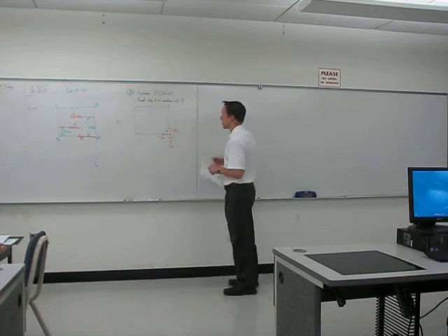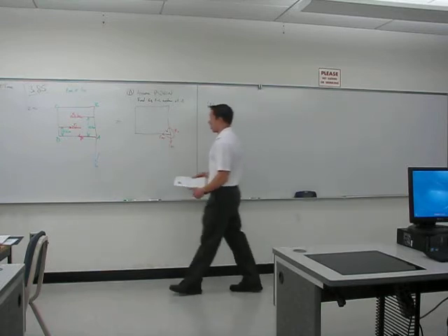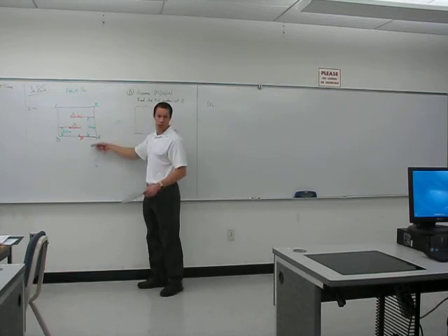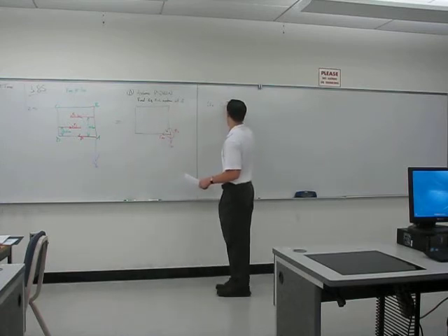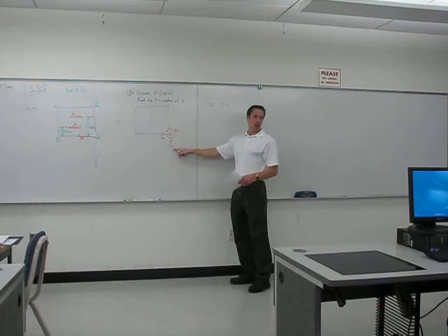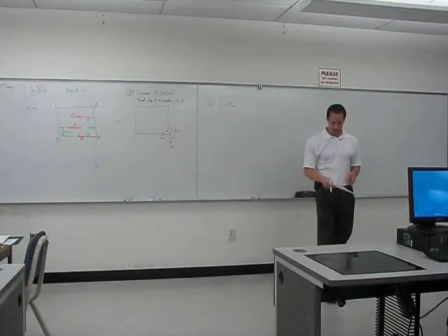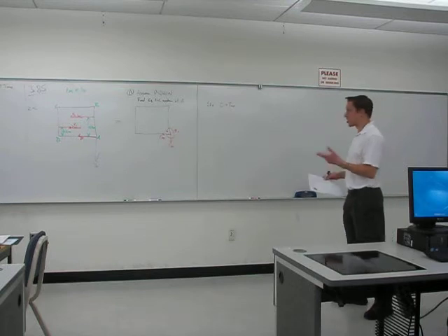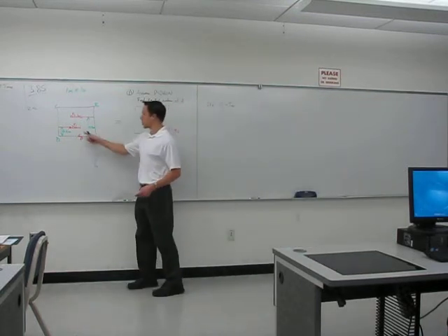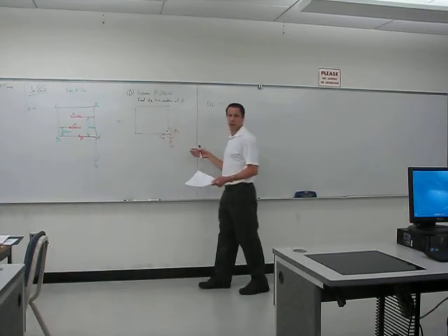So we might say the sum of the forces in the x direction. Okay, so the x direction, positive x is going down. Nothing is going in the x direction in this picture. All the forces are horizontal, so they're all in the z direction. So I'm going to have 0 on the left-hand side equal to, in the x direction, FAX on the right-hand side. So that just tells me that the x component of the force that will be at A is 0. And that should make sense because if you move all three forces to the point A, they're still all going to be horizontal forces, so you're not going to have anything in the x direction.